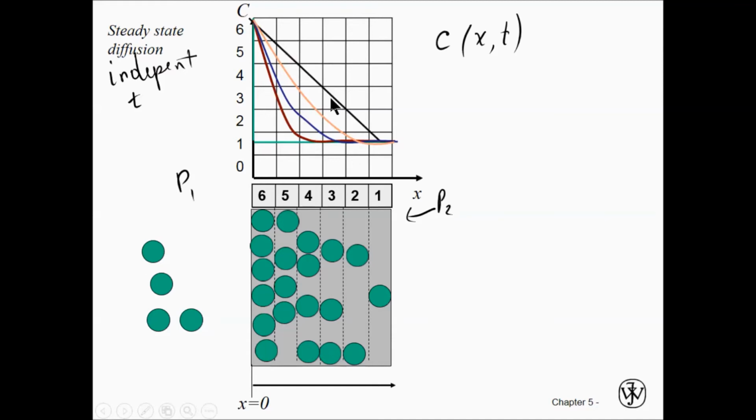So that's the point diffusion becomes steady. It starts as non-steady but reaches a steady point where I have this straight line. What will happen if I continue this process? If you see, whatever comes in goes out. This atom doesn't stay inside. Concentration does not increase.